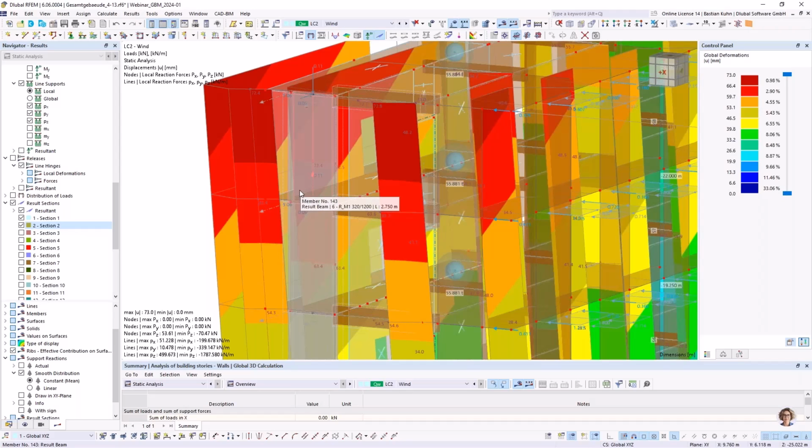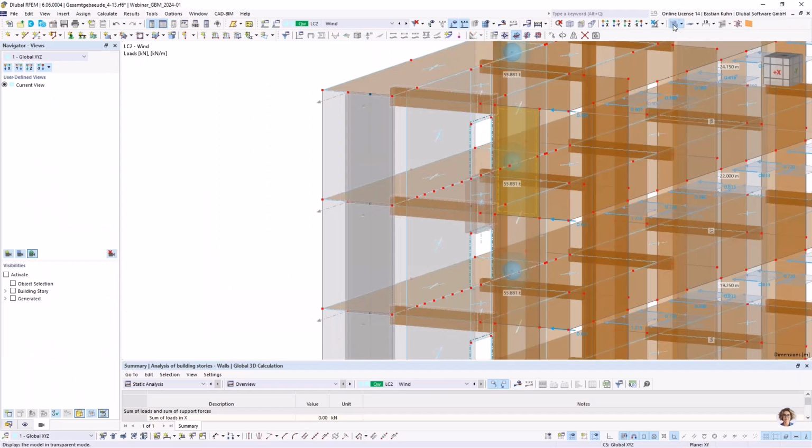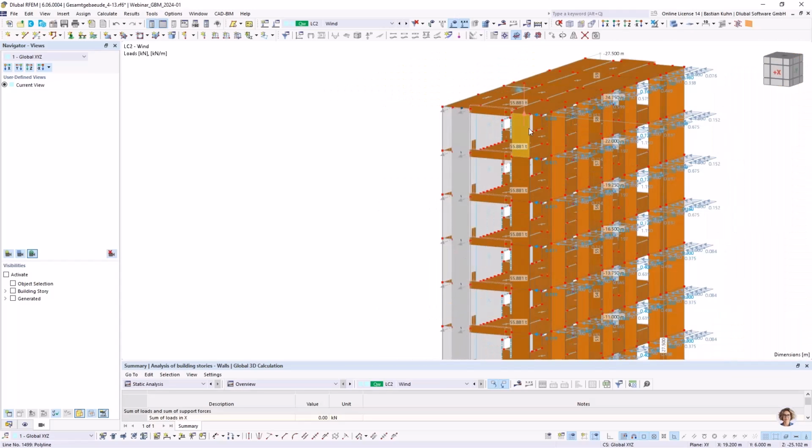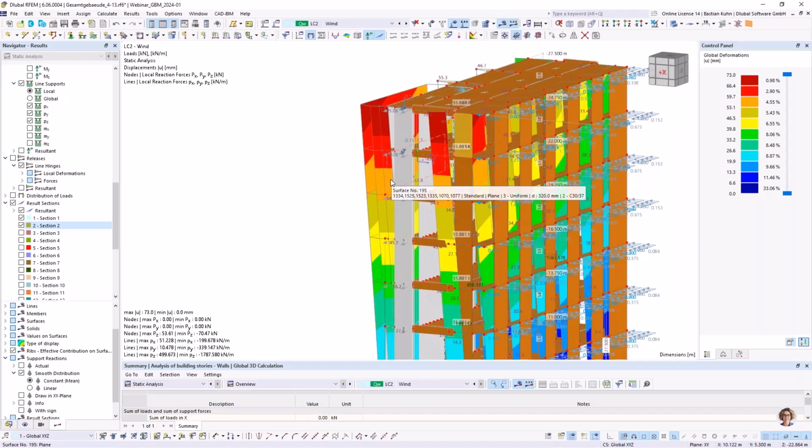And whatever you define how the shear wall looks is up to you. When I'm saying, okay, this wall in here, for example, I don't want to bear any force, you can always deactivate it via the structure modification, or you can reduce the stiffness of it. So this would all be possible, but it is in this 3D calculation, but you are looking onto it only in 2D, on slabs and walls. So this is how you would do that. Okay.